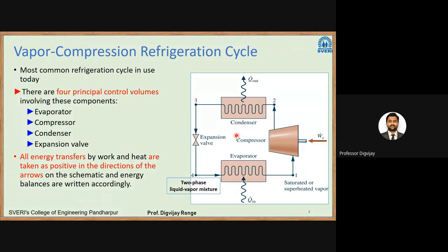The compressor is replaced by an absorber and a generator. In that case, we use energy either from solar energy, or by burning fossil fuels, or we use waste heat from industry or from the space that is coming out. So we have ready energy in our hand. If I am using solar energy, it is available in abundant amount. I will take the solar energy and give it to the generator. In that case, this dependency on grid connection is eliminated.